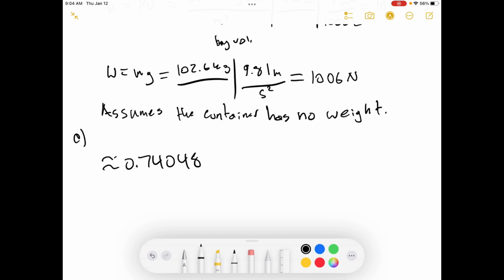That's one consideration. The other consideration is that ball mills have a ton of surface area. In the transfer and handling of those bags, putting them into the ball mills, and having all those balls coated with this really fine powder, you're likely going to lose some material.